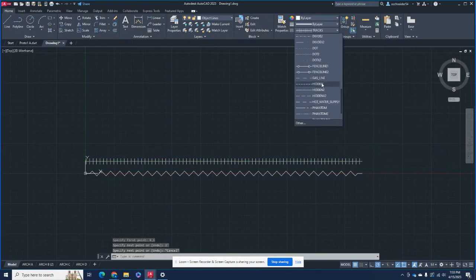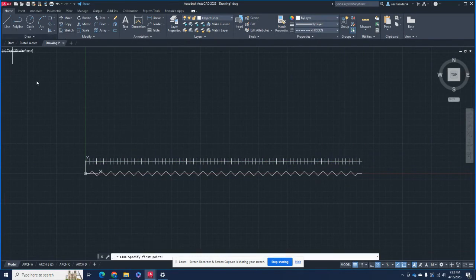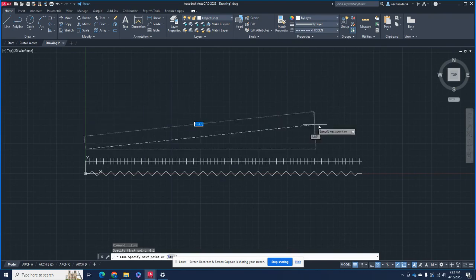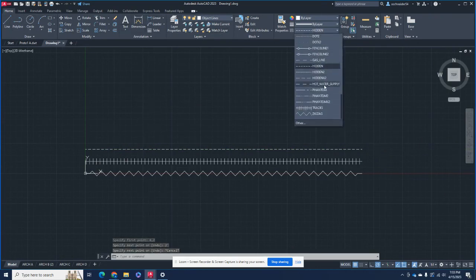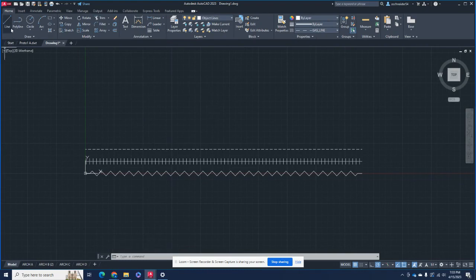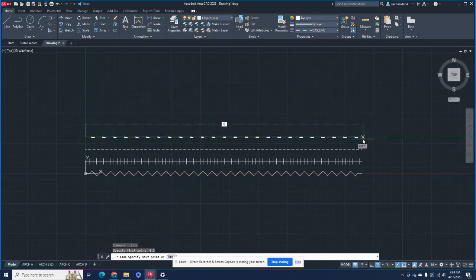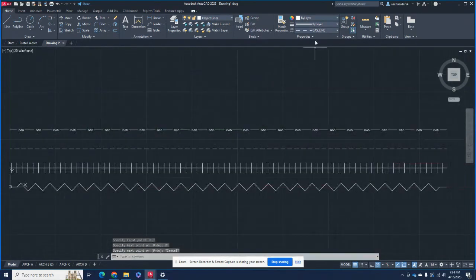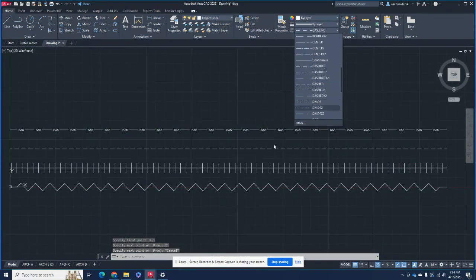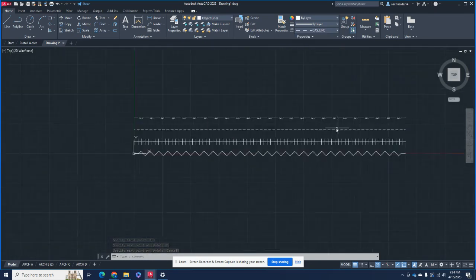Let's go to the hidden line type. Over to the line tool, do 0, tab 2, enter. Then we have this, 2 foot. What next should we do? I'll show the gas line next. 3 foot. You see here on the gas line, it actually writes out the word. And then, of course, I can continue doing this for however many I wish.